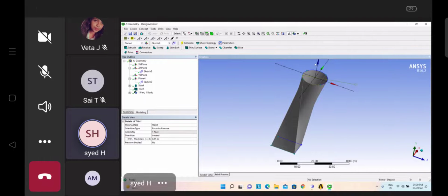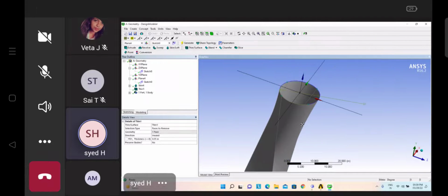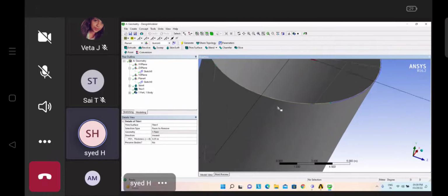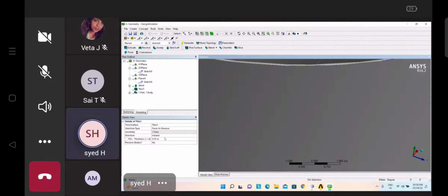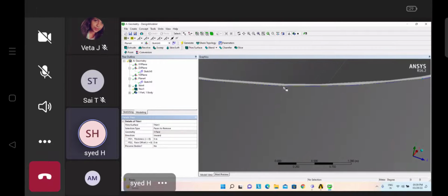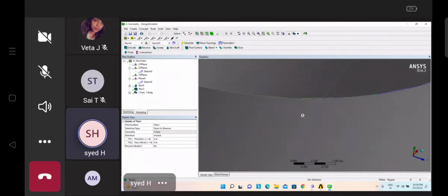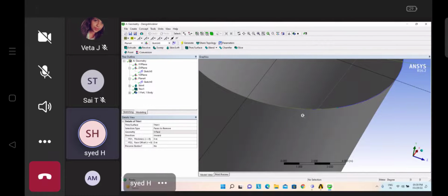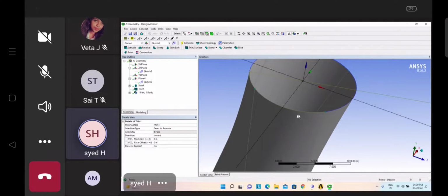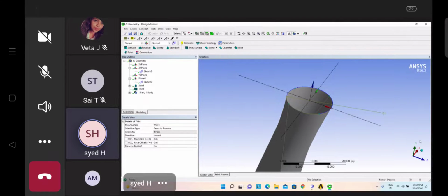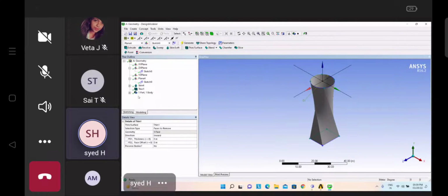So like that. Right now we have given the thickness here as 0.5. That's the reason it's coming like this. You can find the thickness here. Instead of this one, if I give the value as 0, it will make a surface. Here I can find thickness. Right now you cannot find any thickness. So based on our requirement, we can either make a surface or a thick body, a sheet body we can say. So like that we can do things, thick or thin surface.